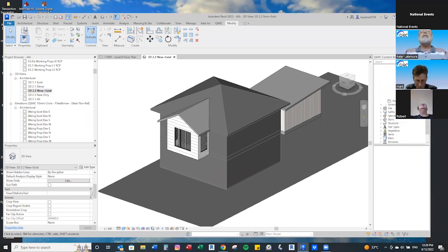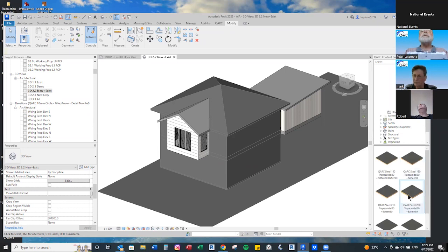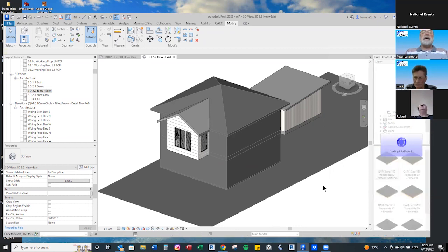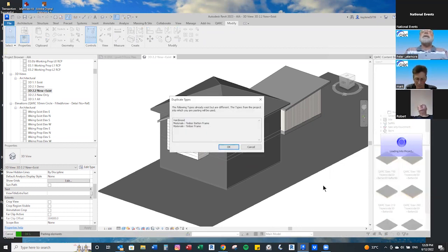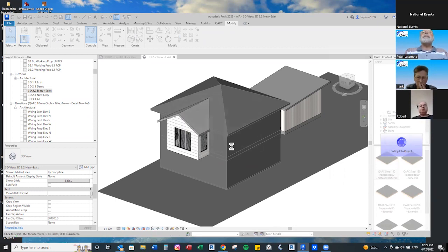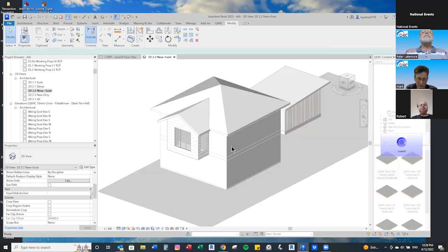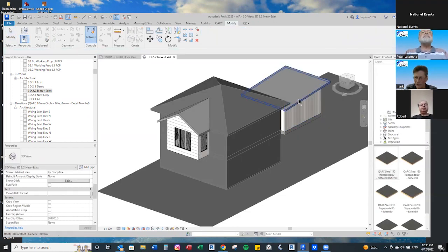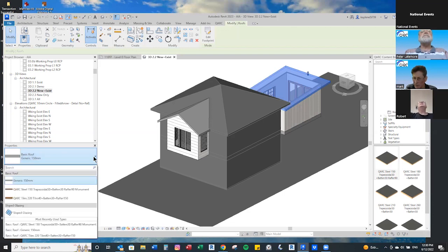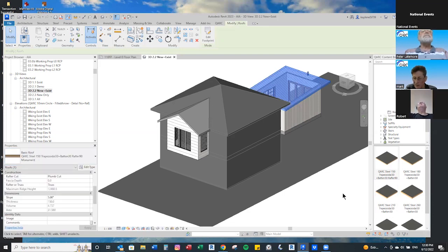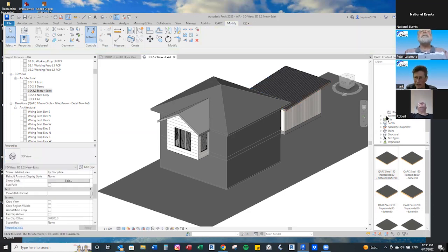And as Kayleen just quickly does some changing of the roof here, we would also like to mention that our system families, particularly walls, are preset so that the top and bottoms are unlocked, so they automatically can be extended. Now, we're going to very quickly go into a roof, and you'll notice on the right here that we've got different roof thicknesses and different systems. So you generally, again, you want to make it once, you don't have to make it again in the future. And you'll notice all the colours on the side there.